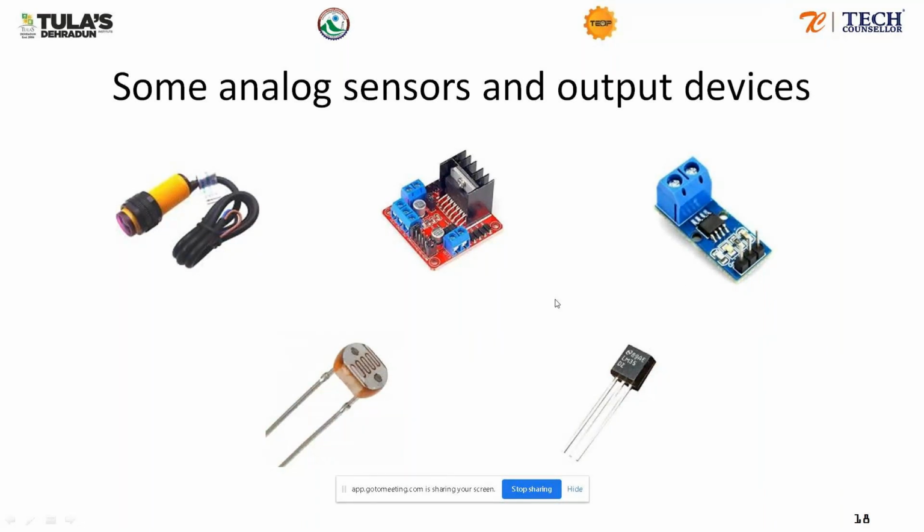5 volts will be achieved when the sensor is at its maximum temperature, 150 degrees Celsius for this sensor. It will return 0 when it is at 0 degrees Celsius, and so on. So I think that's about it for the analog sensors and digital sensors.